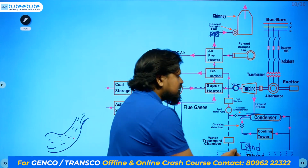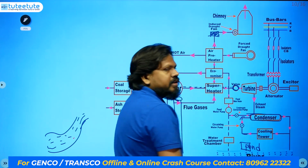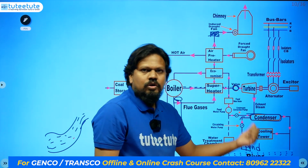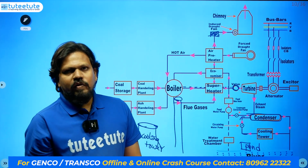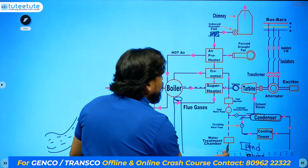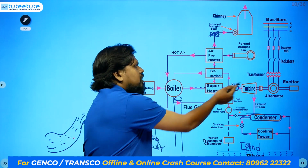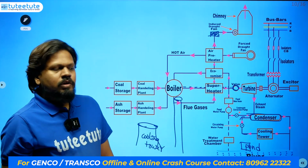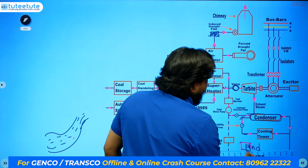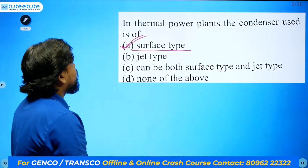Why is water required? Because the condenser and cooling tower continuously change this exhaust steam into hot water. For this, water is required, and that water we have to take into the boiler for conversion into steam. This is the reason. So what they are asking is about the pond requirement, the spray pond they have given here.